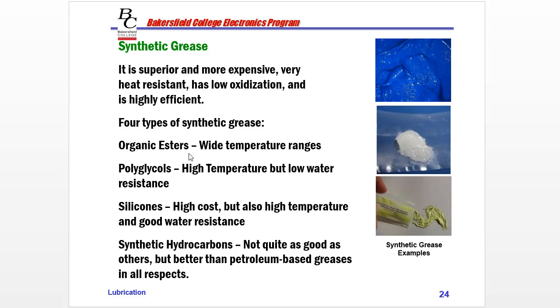They are organic esters, so that has a wide temperature range, polyglycols, high temperature but very low water resistance, silicone synthetic grease, very high cost but also high temperature and good water resistant. And then synthetic hydrocarbons, so not quite as good as the others, but better than the standard non-synthetic petroleum-based greases.